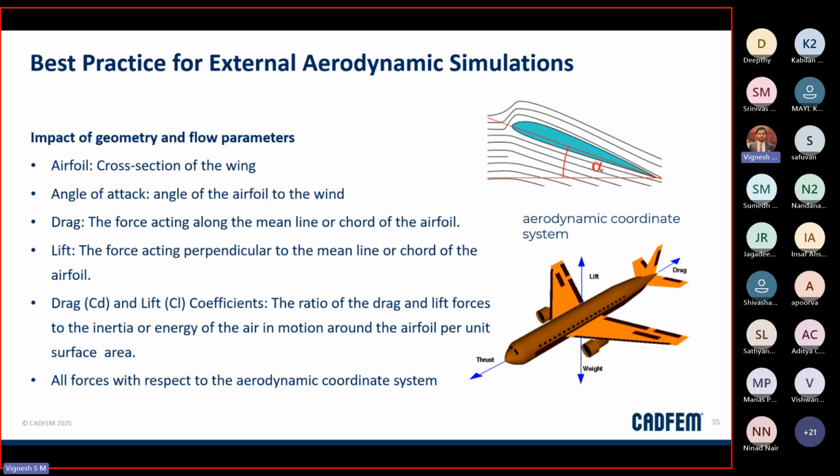That's very important. And make sure you respect the CL/CD ratio. CL and CD can be solved, but the ratios need to be calculated from our side, and only the aerodynamic forces will be obtained from the solver. So you have to balance your calculation on the weight to lift ratio and thrust to drag ratio.